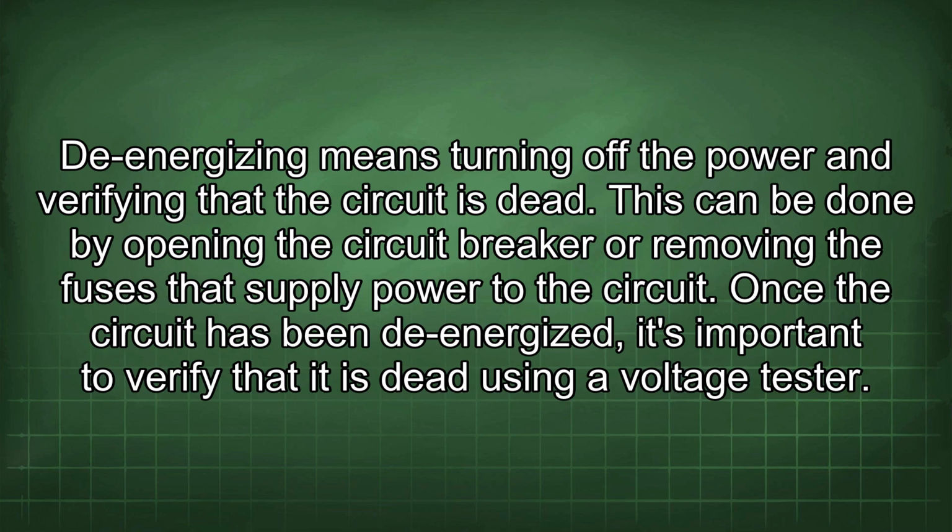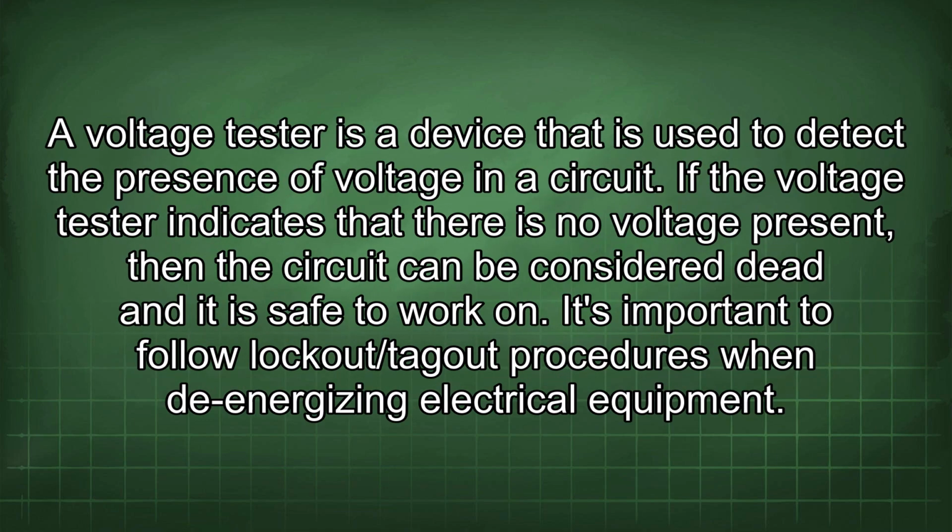Once the circuit has been de-energized, it's important to verify that it is dead using a voltage tester. A voltage tester is a device that is used to detect the presence of voltage in a circuit. If the voltage tester indicates that there is no voltage present, then the circuit can be considered dead and it is safe to work on.